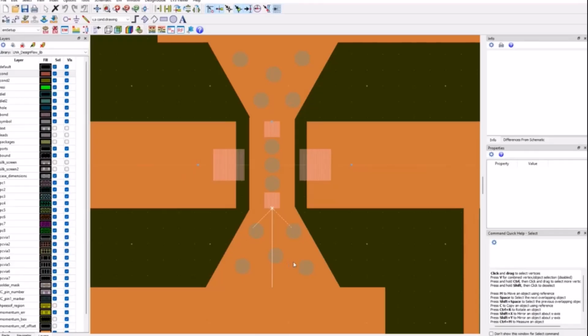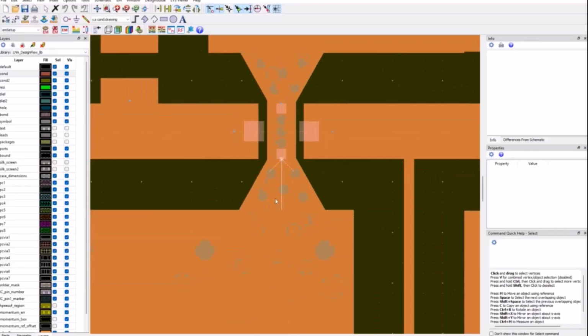Put as many via holes as you can closer to the device, so that you get the least resistive path to ground. Okay, don't be like, I only have one via or two vias and I will be okay. If you do this wrong, the whole amplifier can become an oscillator very quickly. So have a lot of via holes right there.